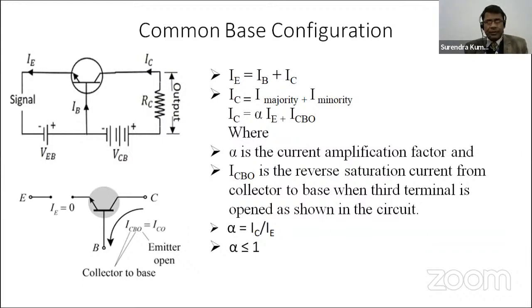In this circuit, first let's know about the biasing technique, what kind of biasing technique we use with the transistor while we are using it in our circuit. So always the emitter base junction of the transistor should be forward biased, and the collector base junction should be reverse biased. If we bias the transistor as per the technique I have just discussed, the transistor can be used in the active region.